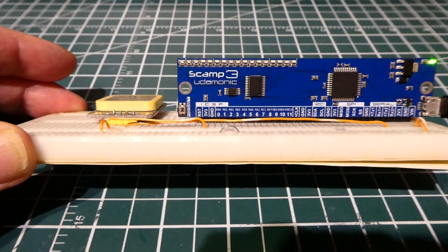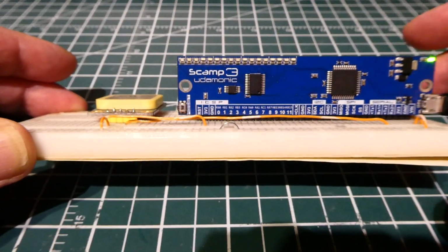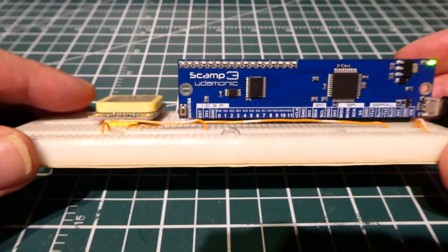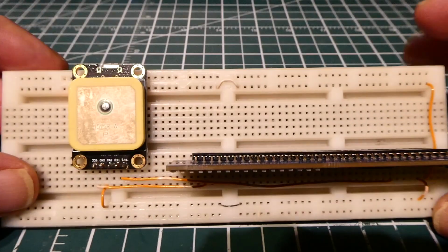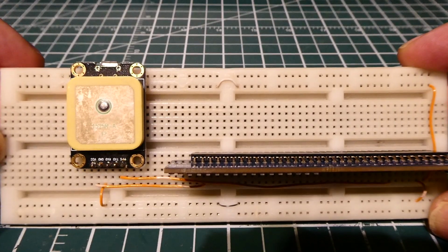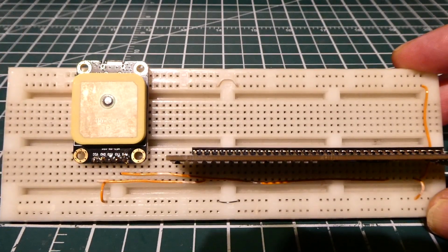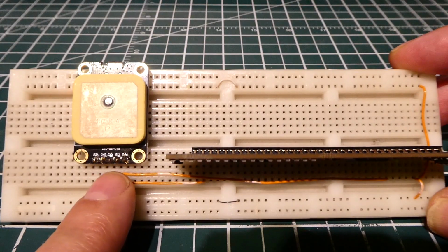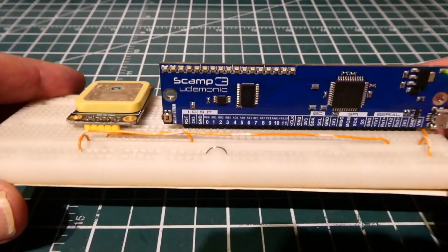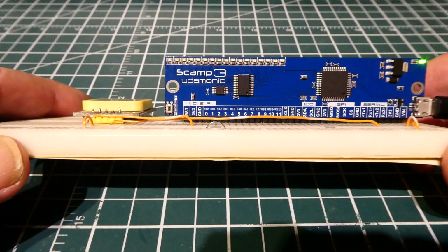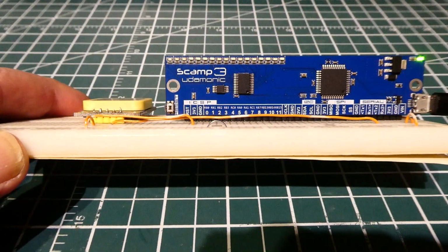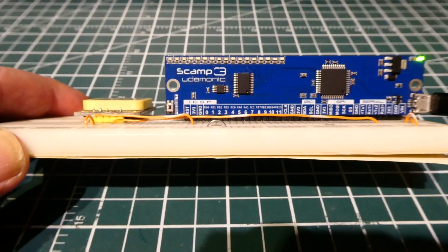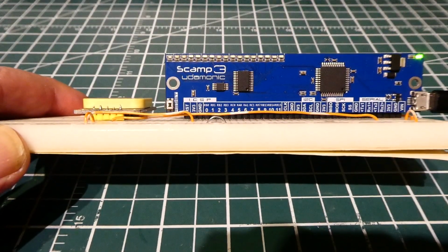Okay, so that was my little tutorial on how to get started with GPS. So now you can incorporate a GPS in your project. You don't have to use this specific one because all GPSs have the standard output, the NMEA 0183 protocol. As long as you get the baud rate correct and it's UART compatible, you could feed it into the Scamp3 board and run the same code. Then you could check out the strings, and you could use the chart to decode the strings to pull out the different fields, or go online to that website and it will decode the strings online.